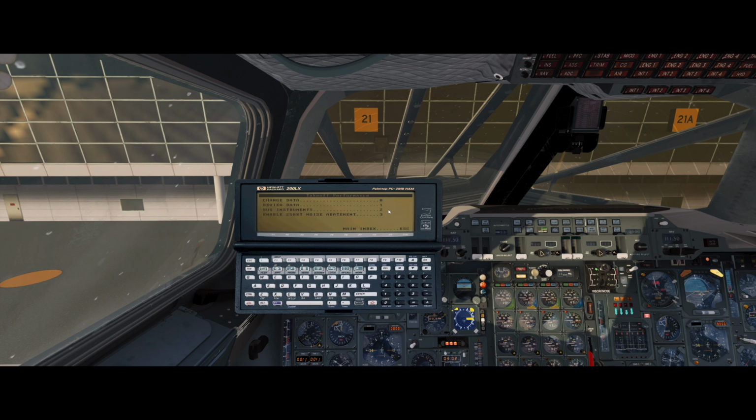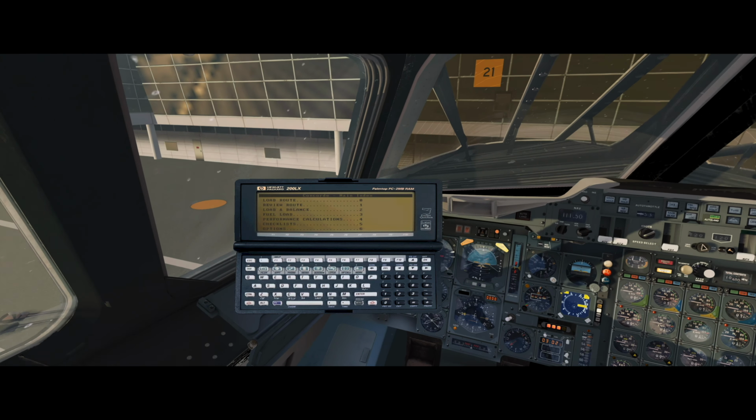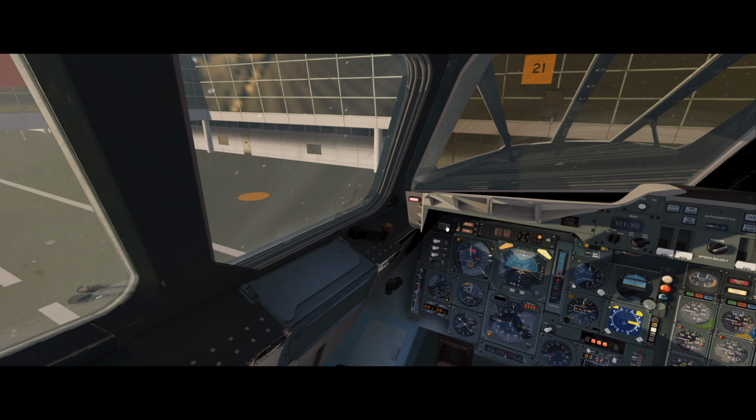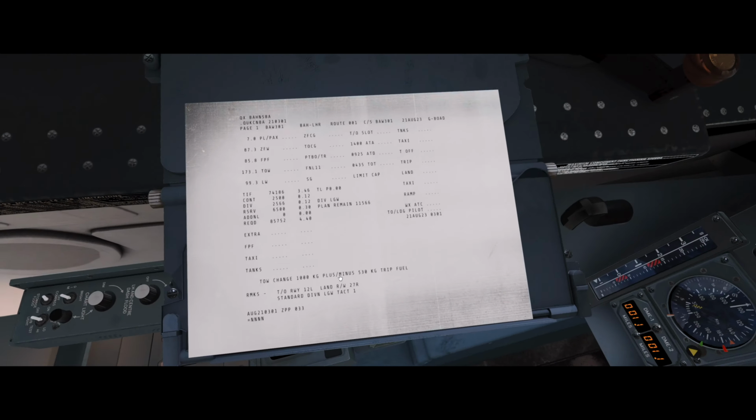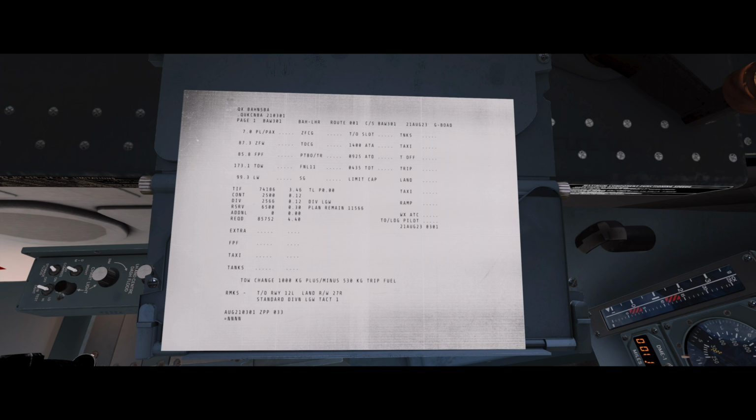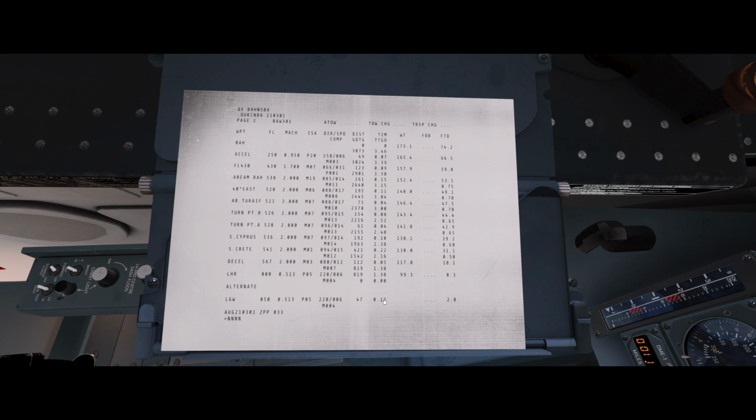We're going to use the standard Concorde departure, and we can go bug our instruments by pressing the 2 key. This will set everything up, the timer. Well, we have no timer today, but the pitch index, the fuel flow, P3 bugs, and the airspeed bugs most importantly. You can also bring up the charts and everything else related on this little side panel here. As you can see, we have a zero fuel weight, takeoff and landing fuel, and our landing weight, and all the different types, or trip fuel or contingency.